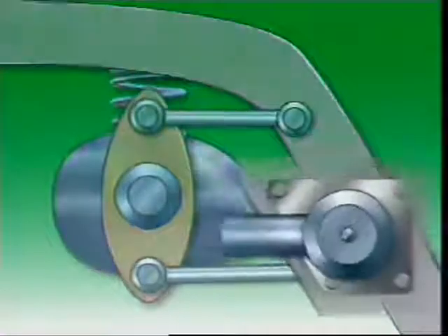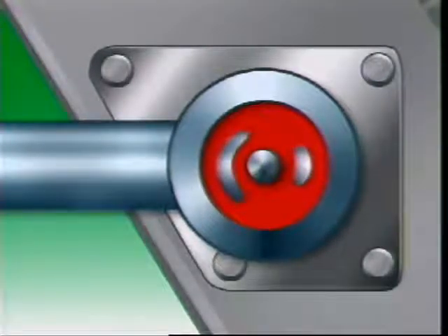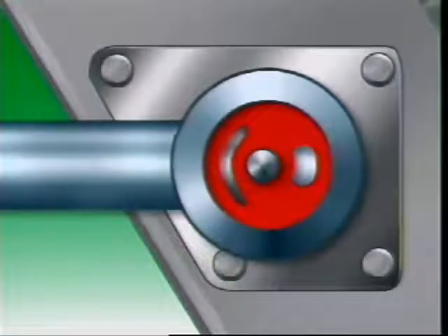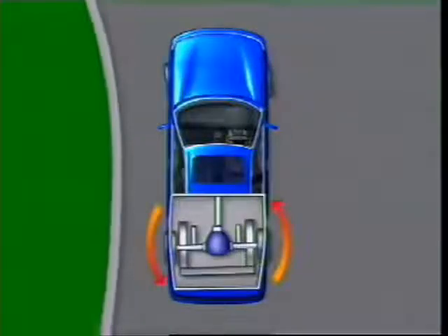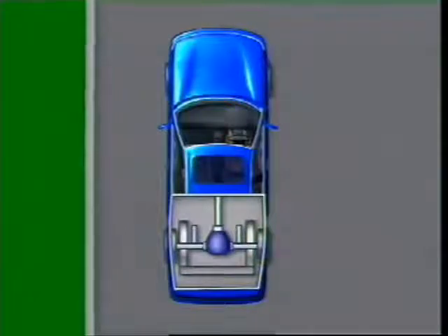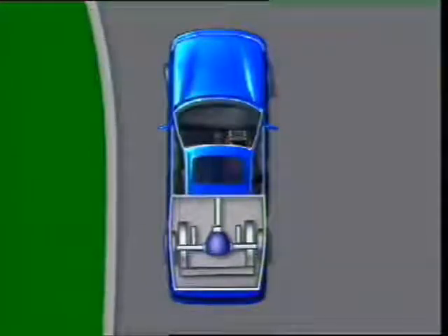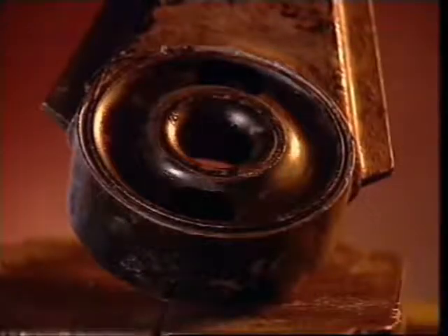In control arm applications, particularly at the rear of a vehicle, the rubber arm may be moulded with a voided section. This is known as a compliance bush because it allows the unit or component to comply with a controlled amount of movement in the direction of the void. This movement relative to the vehicle frame allows compliance or deflection steer of the road wheels when cornering. Since this influences the steering behavior of the vehicle, it is very important the voided section is in its correct relative position.